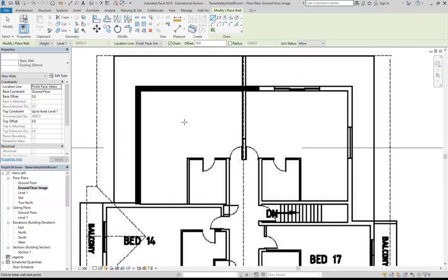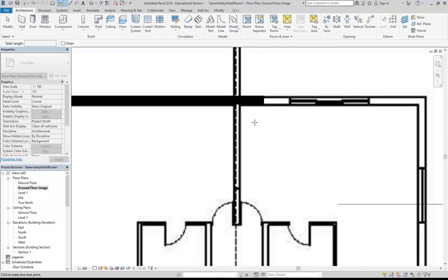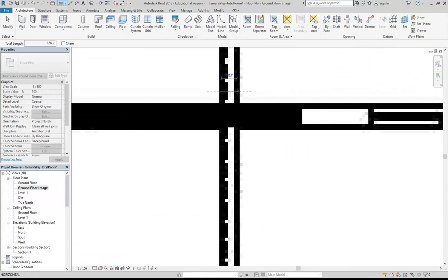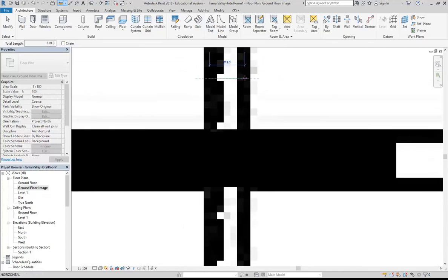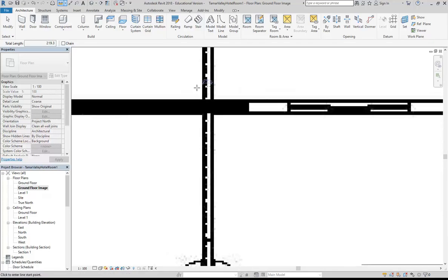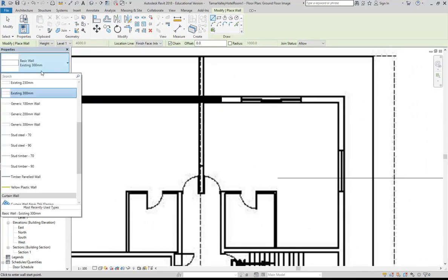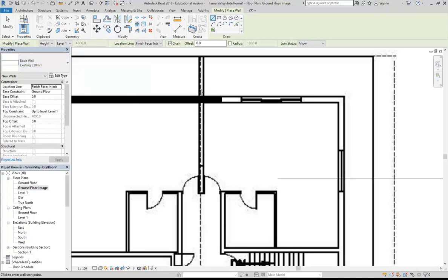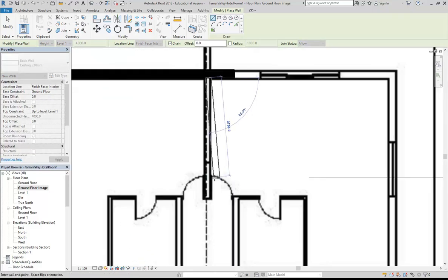Yeah. Okay, so I've done a couple of walls there, and I'll then just switch over to the measuring tool and check this wall. So that's a party wall, so that won't be the same thickness as the exterior wall, so it looks like it's about 220, maybe 230. Yeah, I'd say it probably is 230. No, it looks like they've drawn it 220. Okay, so we'll do that. So again, back to the wall tool, and well, we've got existing 230, so I will use that, and that's close enough anyway. So I'm just going to draw by tracing the plan by eye.